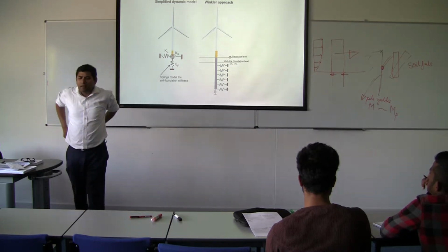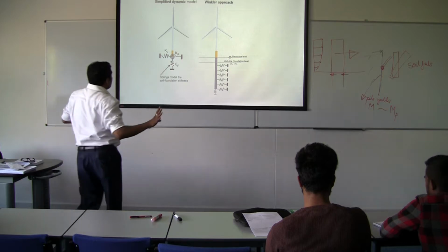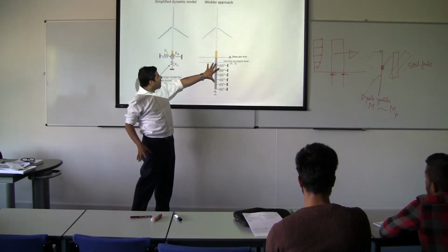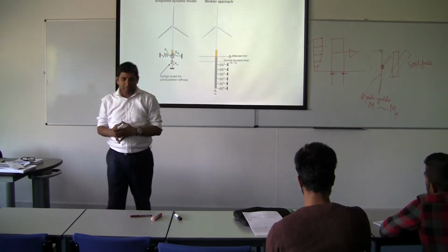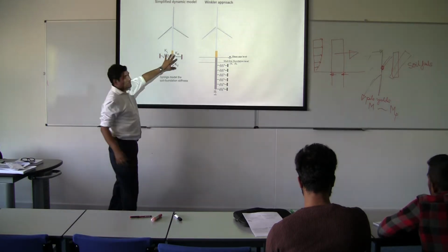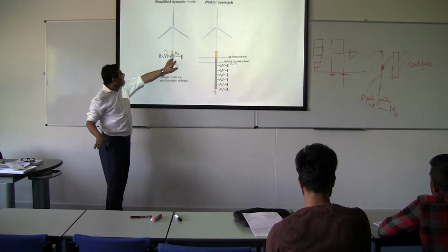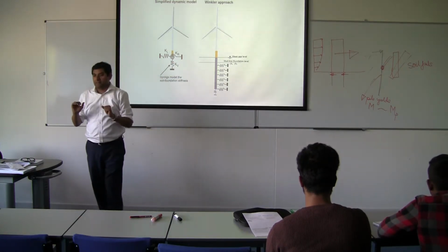So if you see in most engineering practice, what will be done is effectively you will model the pile. Suppose it is done by somebody doing structural engineering. So they would set up a model like this. They will ask geotechnical engineers, give me pile stiffness springs.